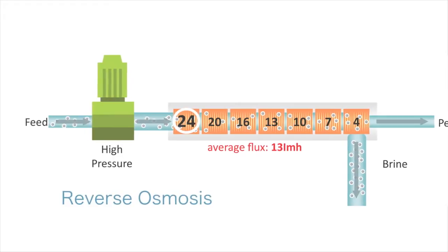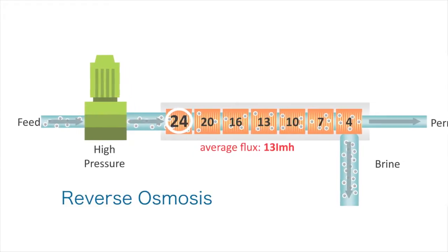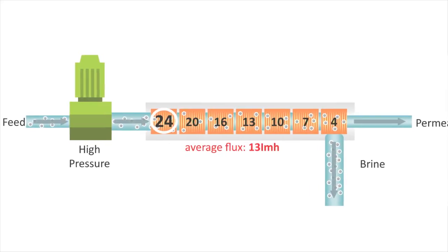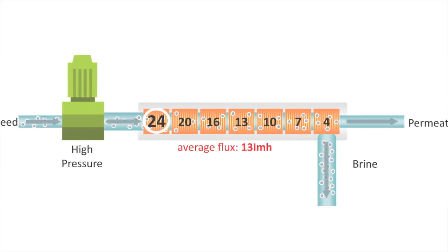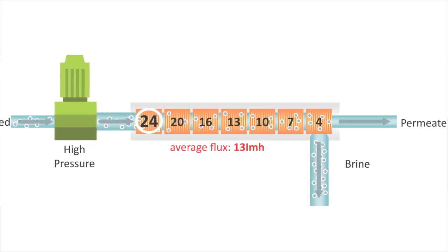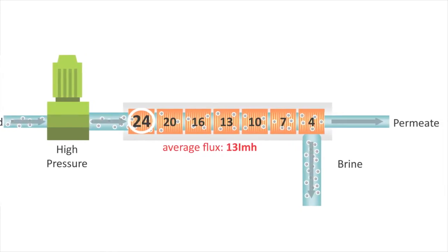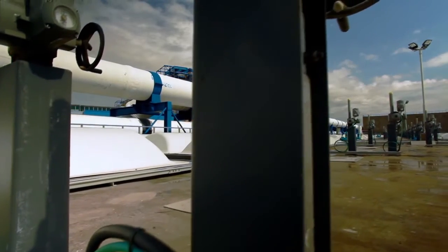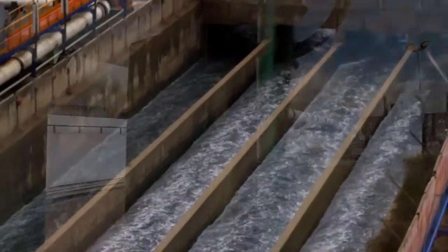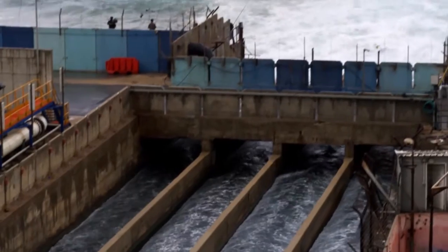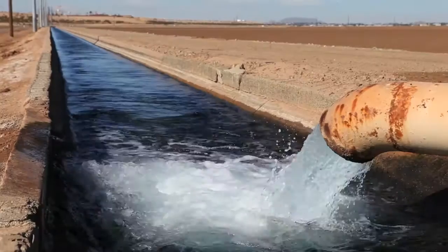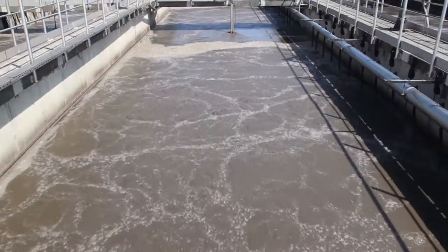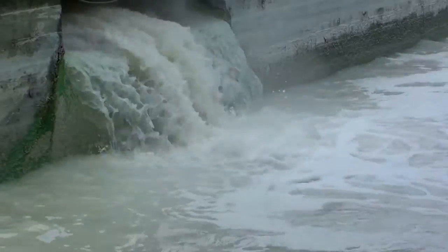Reverse osmosis, or RO, uses a different mechanism and a special filter to clean water. Instead of feeding water directly to the filter, water flows along its surface, constantly sweeping away concentrate that accumulates, while only a small portion of the flow actually passes through the filter surface. RO is effective at removing dissolved solids and does not require purging. However, the need for cross-flow results in a substantial waste of water and energy.